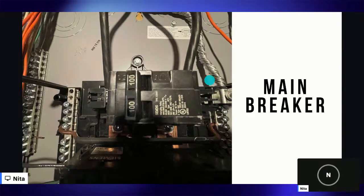Okay, what is that silver wrapped wire on the right? This right here is the neutral. This is stranded aluminum. It isn't supposed to be wrapped; it can be, but it doesn't have to be. This is stranded aluminum. It is our neutral. You will be able to tell because they're going to be the largest conductors in there, whether they're sheathed or covered or not. 2 hots, 120, 120, and the neutral.